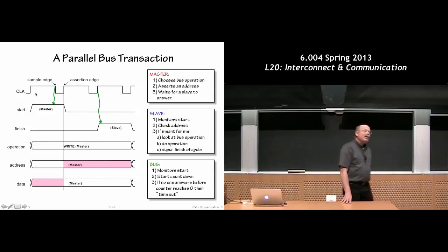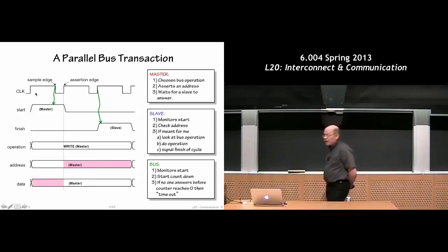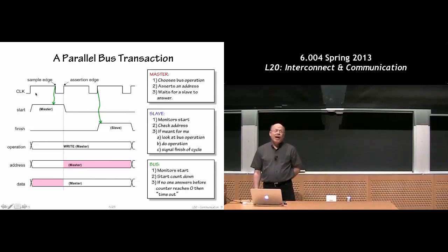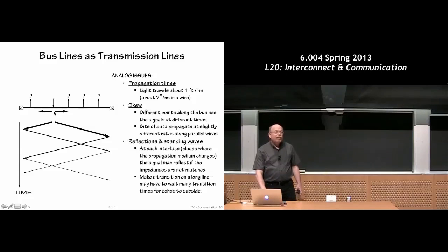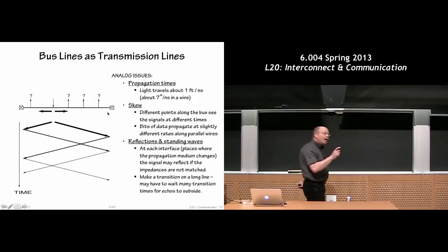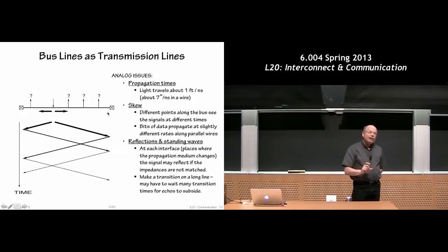It didn't work much past a 10 megahertz transmission or maybe a 20 megahertz transmission. It didn't work very well after that, simply because it took too long for the signals to propagate down these buses. And there's a bunch of issues. One is that there's the physical propagation time. The second is all the connectors on these buses introduce these small impedance changes in the bus.